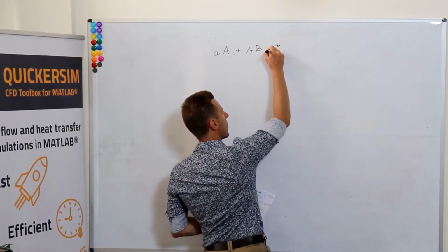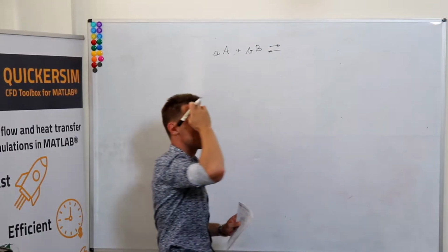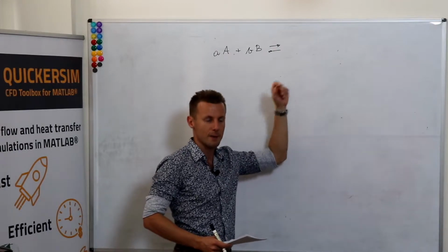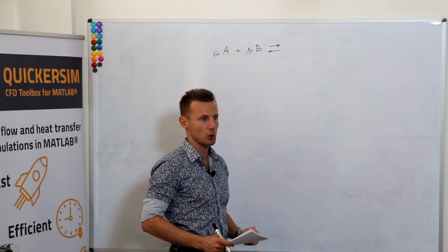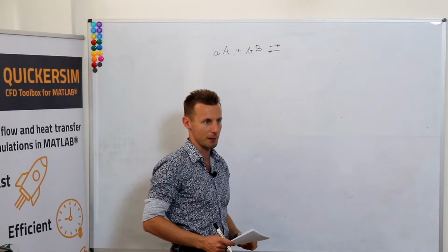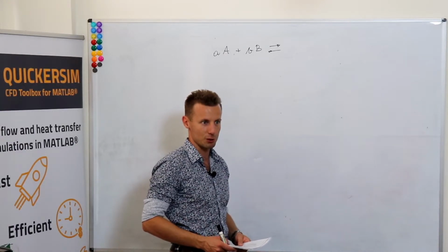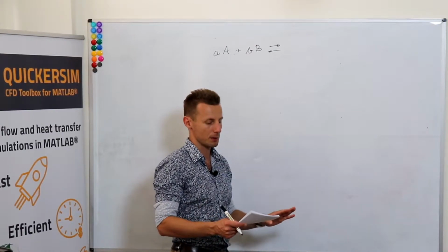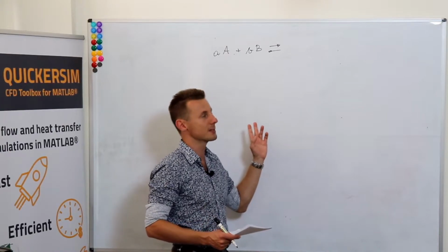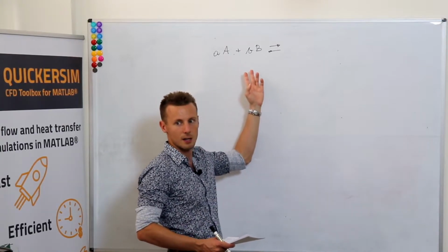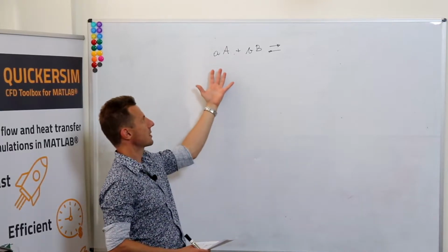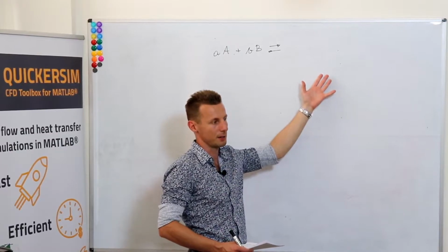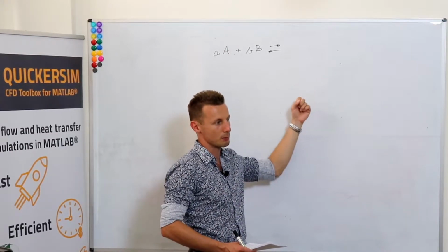Then one remark: remember that very, very often you will see reactions that are written just in one way, but the reality is that you cannot implement them in the CFD code in just one direction. Because really how it works, I'm not a chemist, but chemically, you are turning the substrates into the products, but actually the chemical reaction stops when it reaches some equilibrium.